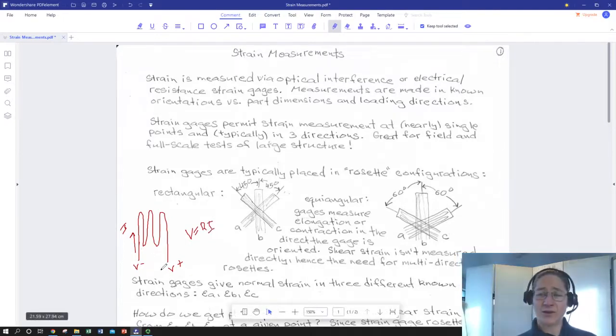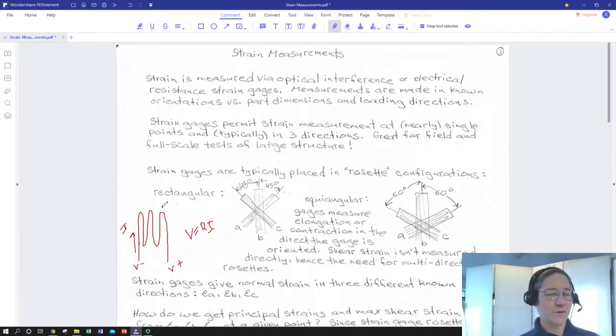So if we're applying a known voltage and measuring current, then the current that we would measure is a function of the resistance. And we know that resistance of any kind of conductor is going to be the resistivity of the material, which is a material property, varies with temperature, somewhat with strain, but not so much, and then times the length and divided by the cross-sectional area of the conductor, which is this fine wire over here.